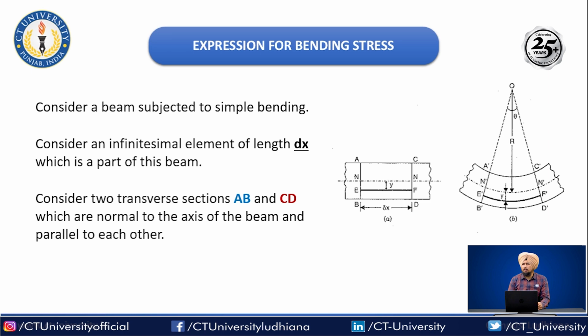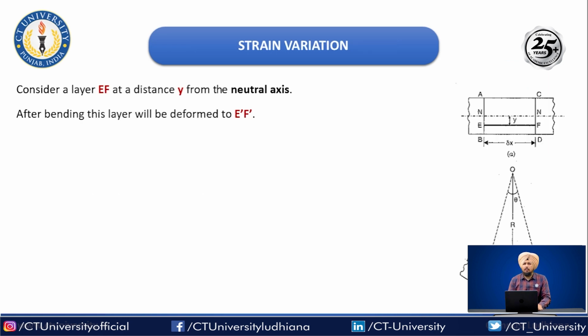Now we have to carefully see that we are going to apply very basic mathematics in this case, to find the length of the layer, and we are going to compare that length with the original length. This is how we will find the strain in the material. If you remember the principles of SOM, we need to calculate stress and strain, and if you know the change in length, we can find the strain in the material. So we are going to compare the two lengths, before and after, and with the help of that we are going to find the strain in the material.